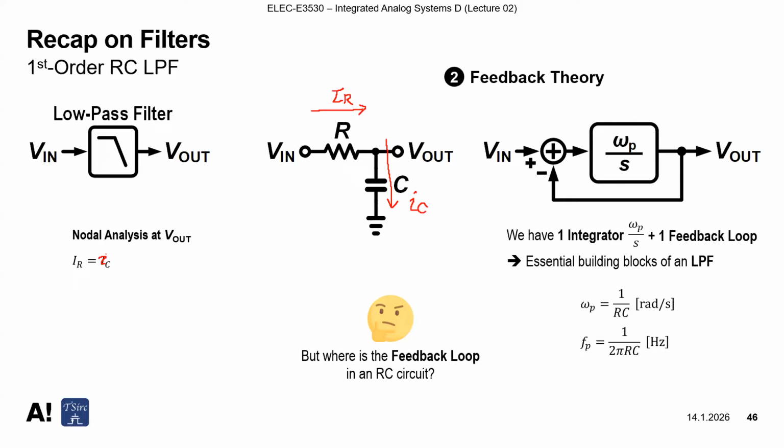We normally describe the current with a capital letter I, saying it is a large signal. But when we take the small i, it means that we are thinking of small signals. This is very important when we analyze the circuit, because any DC current cannot pass through the capacitor. But when we take the AC current, the small signal, then it can pass through the capacitor. Anyway, let's take another analysis of this kind of circuit.